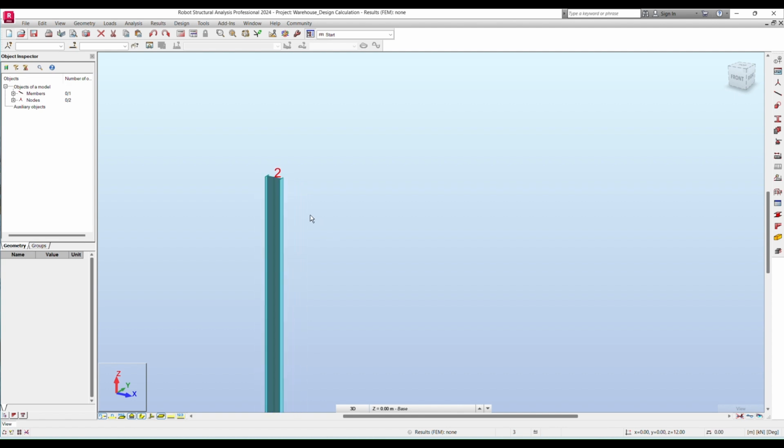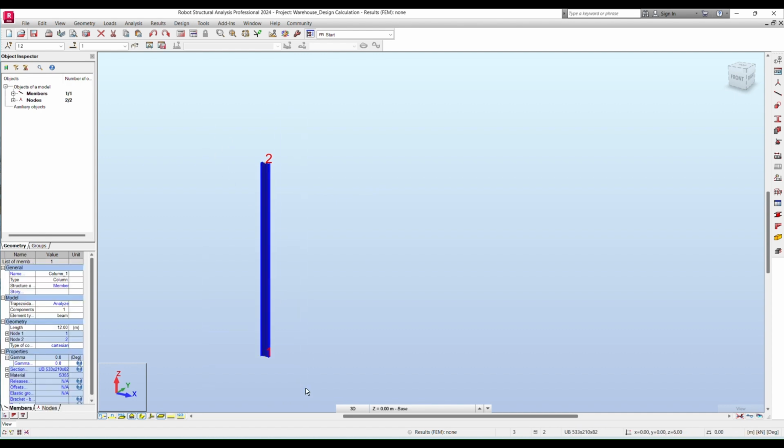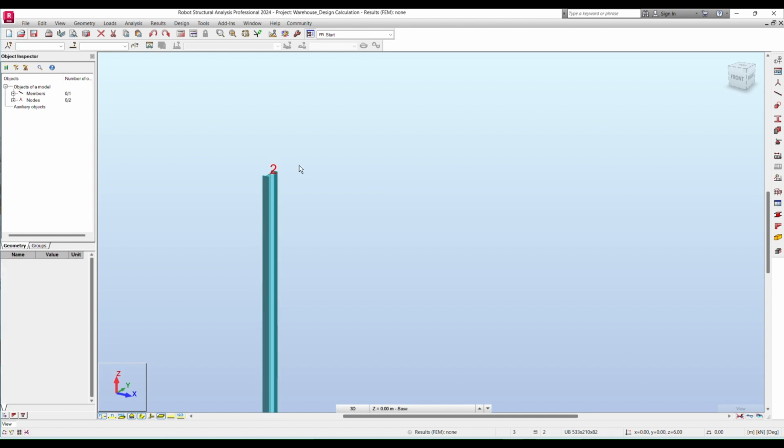Generally, parallel to the length, we are going to provide a column every 5 meters, and we will also provide a tie beam. The maximum deflection in this direction is very less compared to the width direction, because in the width direction we are going to keep another column at 18 meters. So it is better to turn this column by 90 degrees, as here. You can see it turning by 90 degrees.